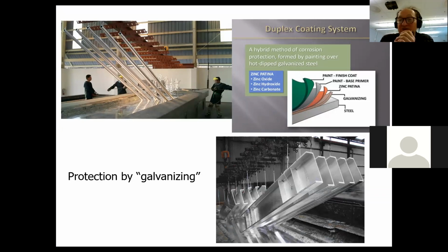So this is the principal reason we use tin plating as opposed to galvanizing. We would never put food into a galvanized tin, even though the galvanizing will probably protect it very well on the inside, because the presence of zinc would unfortunately make the food taste really bad, whereas tin does not do that. So that's the reason we use tin plating in the industry, and we do not use zinc.